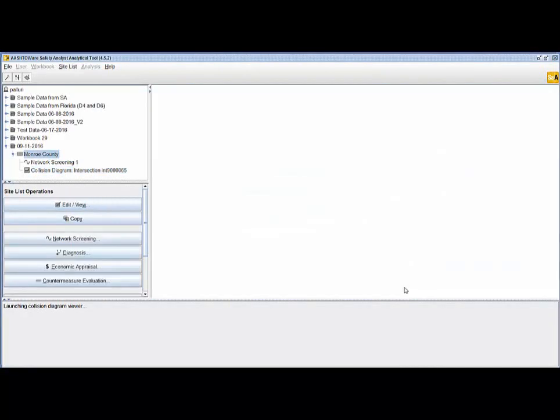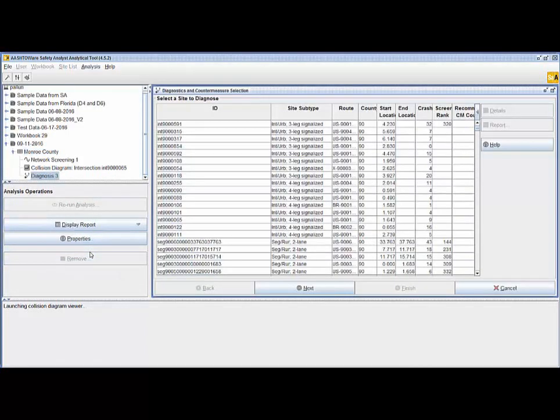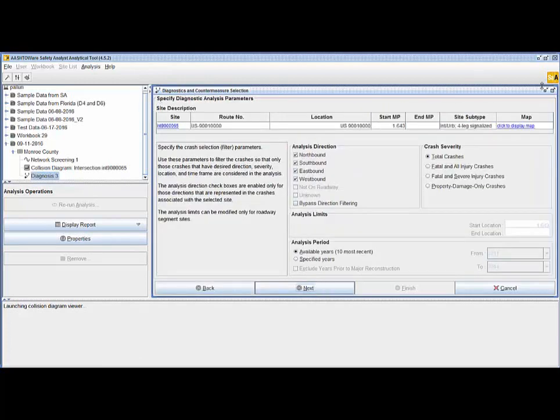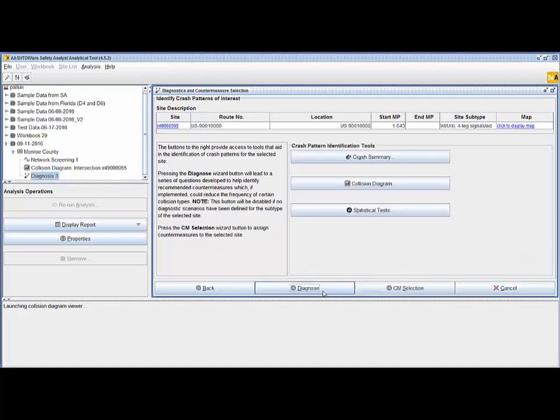Now let me cancel the site list, and as you can see, so far what we had done is we created a new workbook and named it 09/11/2016, and we created a new site list by the name Monroe County. We performed network screening, and then we looked at one site. Now let us perform diagnosis by clicking on the diagnosis tab here. Let me choose the intersection that we have just looked at and click next. A new window appears and asks us to provide diagnosis analysis parameters. Let me leave everything at the default values and click next.